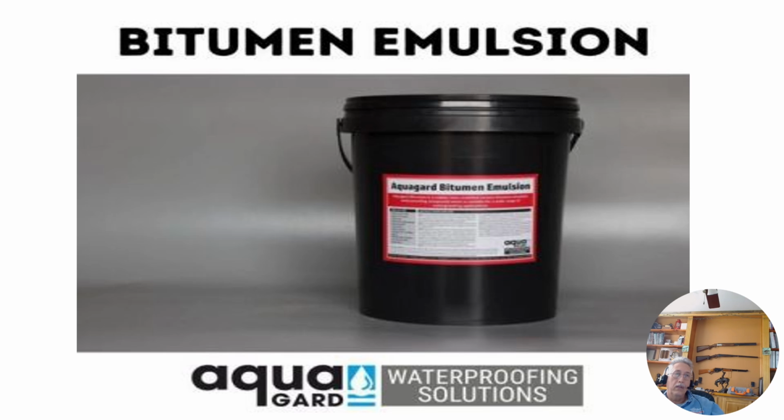And there's what that product looks like. I put this picture in there because a lot of times you'll see these buckets still sitting on the roof after they're done silver coating it or sealing it. If you see anything like that up there, write it up as a defect, because high winds can blow those off of flat roofs and hit somebody on the street below or their car and cause damage. So anything that's not secure on top of that flat roof, you write up as a defect.